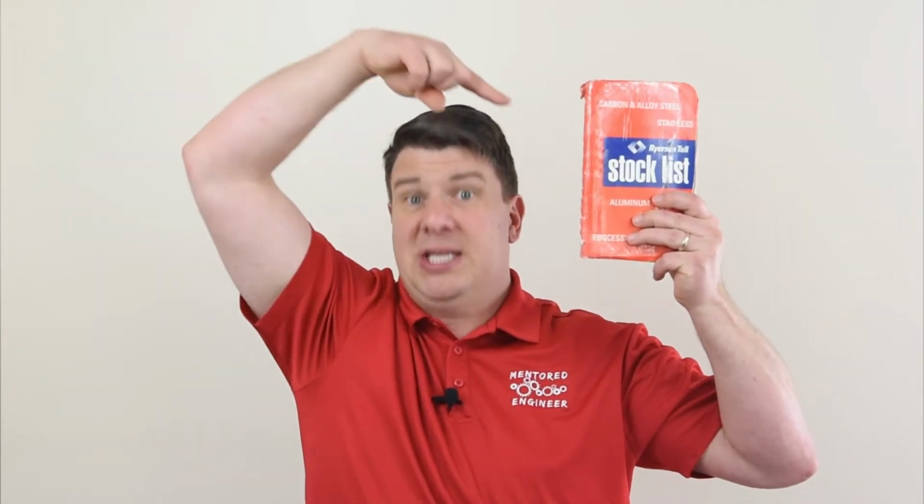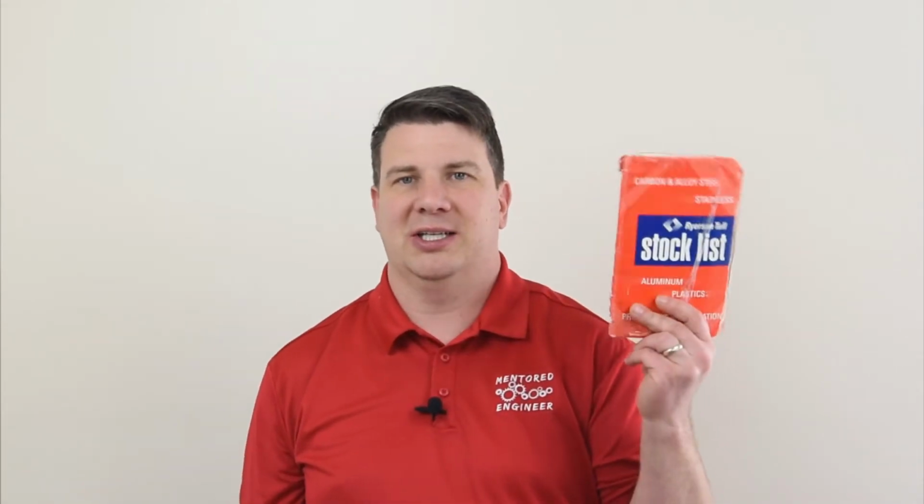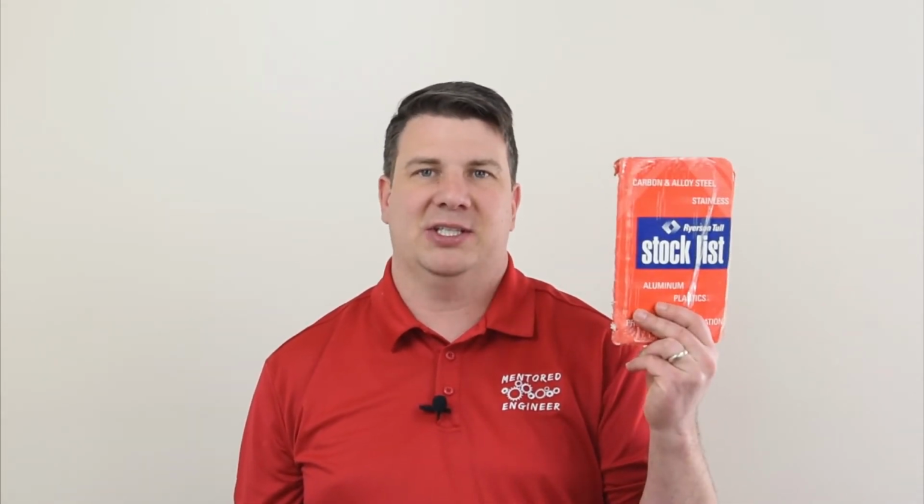So the first thing you need to get is a steel book. It's very important. All right, this one I got in about 2002. It's all but done worn out. I take very good care of this so that it does not wear any further. This is a Ryerson tool stock list. They have this still, even if it's not your local steel supplier. I think you can buy it for $20 to $25. Well worth the investment. Get your boss to pay for it. And you will use this all the time if you specify steels.